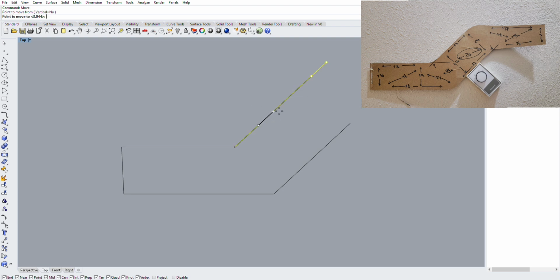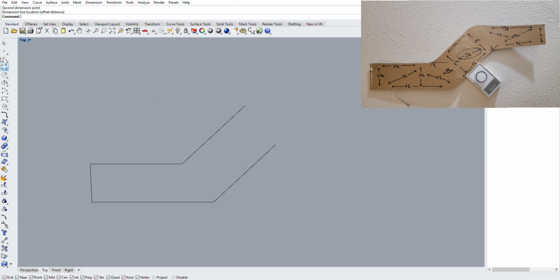So all I did was copy that line from the bottom point, copy it up to the next point, turn on the control points for that line, and stretch it out by 1/8 of an inch. And by doing that, that line's now 8 1/4. This line is 8 1/8. And they're parallel because those lines are already parallel. And we're already more than halfway through this template.